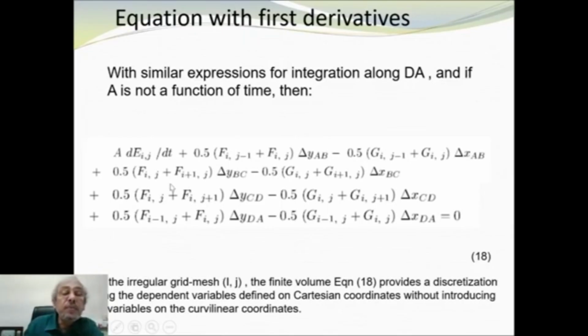We can see that rho u and rho v are all written as expressions on Cartesian coordinates, whatever their values are on Cartesian coordinates, but we are evaluating them on curvilinear coordinates by calculating the net projection of mass in the x direction and the net projection of mass in the y direction, and obviously the net mass flux will be 0, and we are setting that equal to 0, plus these are all spatial derivatives plus the temporal derivative. So we do not transform u, v, w, etc. along the curvilinear coordinate.